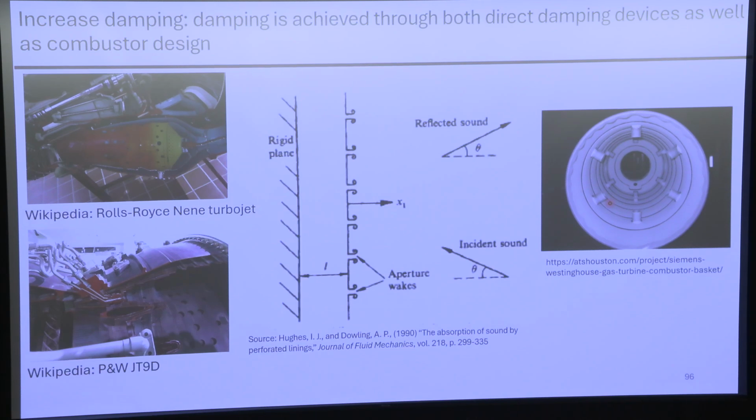There's a few, you've got the crossfire tubes and some dilution jets, but this thing is just a solid piece of sheet metal with a nice thermal barrier coating on it. You've got many fewer holes. So not only did you, by creating a lean premix flame, make the flame much more susceptible to instability, because you're running at really lean equivalence ratios near the edge of blowout and that flame's not happy, but then you took away all the damping by taking out all the holes.